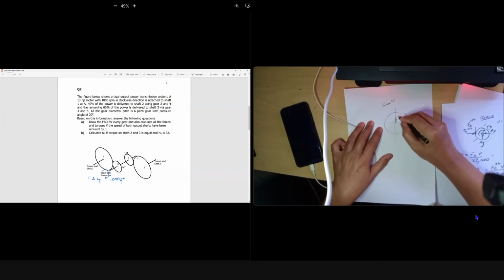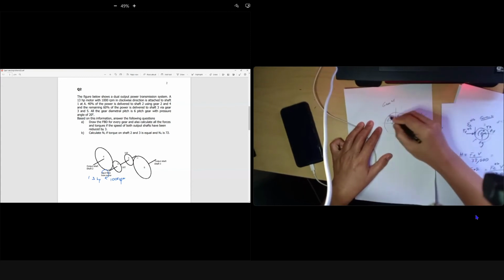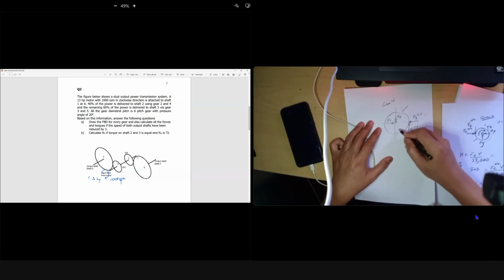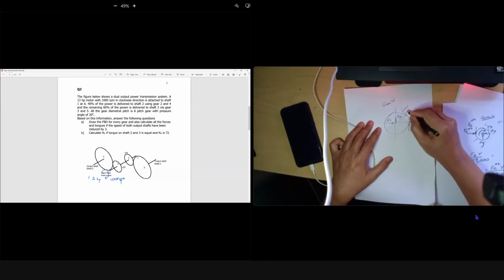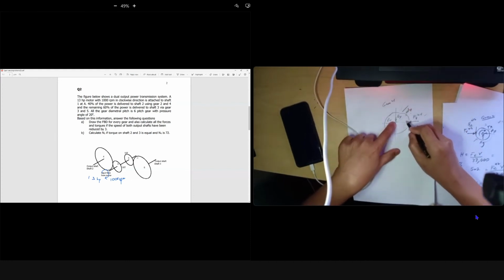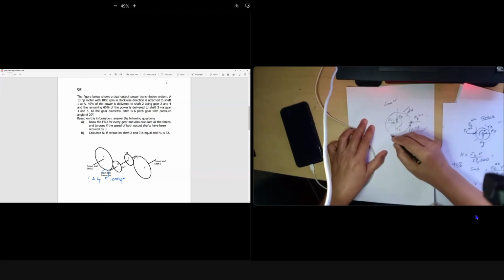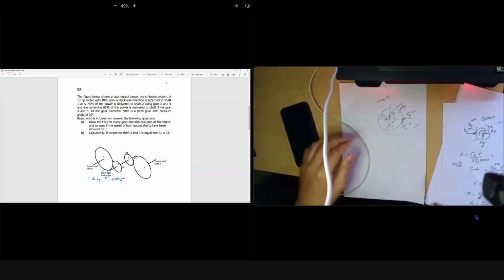So you can know what the reaction is. This will be your BY. This one I do not need anymore. You can get BX. And also you can get what the torque is. This one produces counterclockwise torque. Okay, be careful. You must find the diameter of gear 4. This F produces the turning of your torque, or your moment, counterclockwise. So for this one, the torque at B will be clockwise. I think you know how to find it. Okay, you can solve for gear 4.